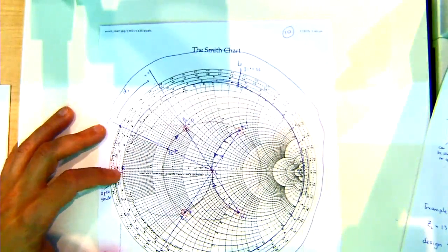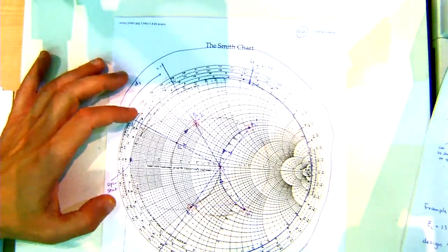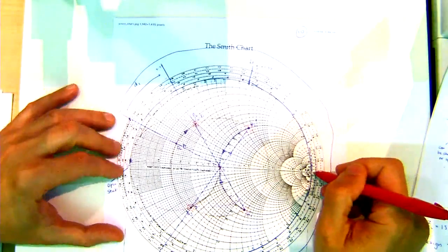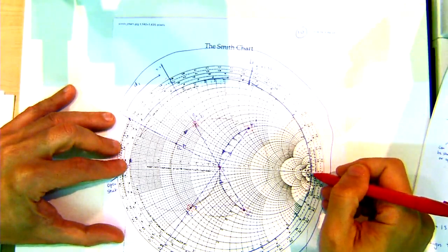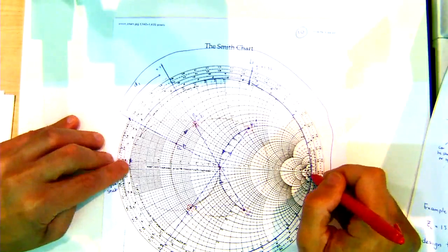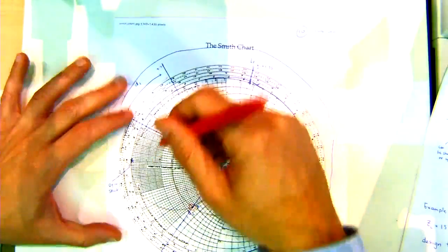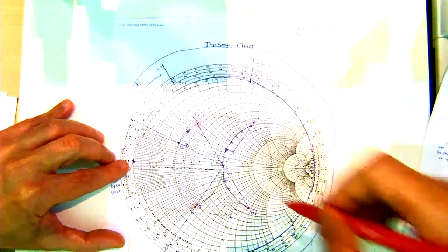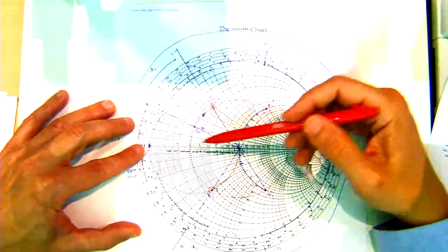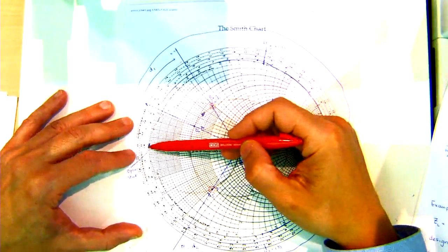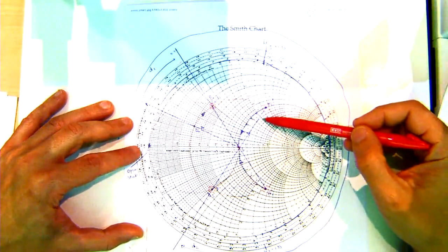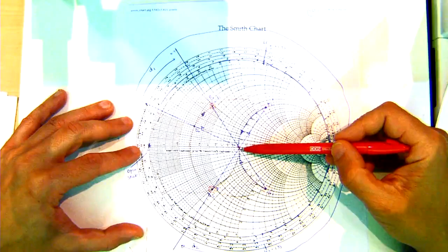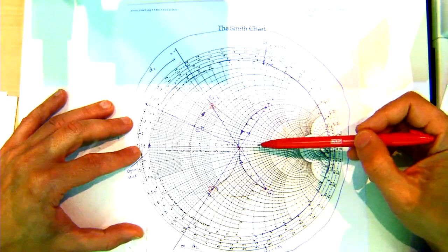All right, excellent. Depending on whether it's a short or an open circuit, and depending on whether it's admittance or impedance, you choose the appropriate point where you start. Okay, we're looking at admittances, right? And we said the admittance of an open circuit stub is 0, and we want to add positive 1.33. How do we find out what the length is?